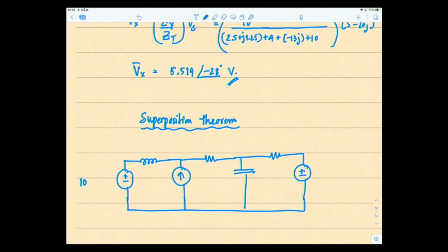This is the voltage source with 10 cos 2t volt, and this is 2 henry, this is 2 sin 5t amps, this is 1 ohm, this is 0.1 farad, 4 ohms, and this is actually a DC source, 5 volt. The question is, please find Vout at steady state.